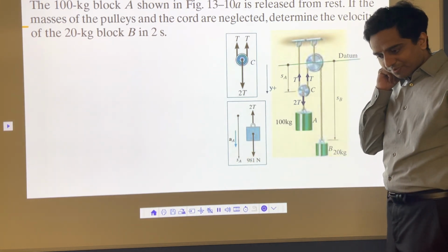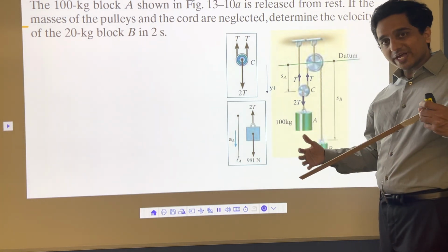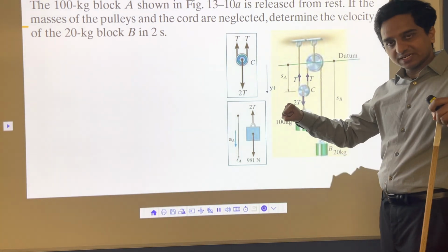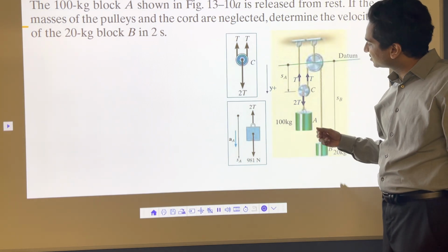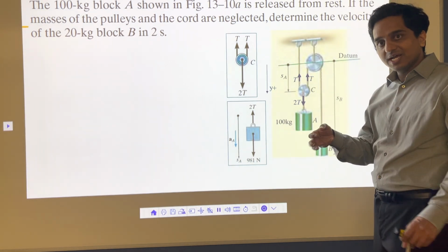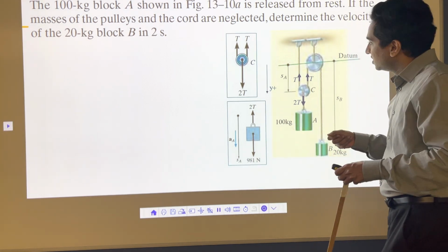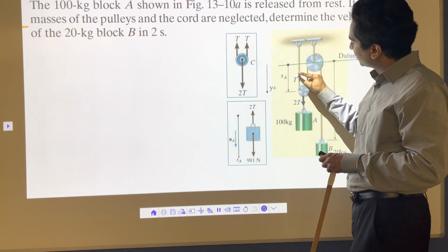Now the important thing about tension force is that it is a pull force. You cannot compress a rope, so a rope always has a tension in it. If you want to know the direction of a tension, you can imagine that you are standing in front of the object and you are pulling the object towards you. That's the tension. So if I am standing in front of the pulley here and I want to pull it, it will look like this.